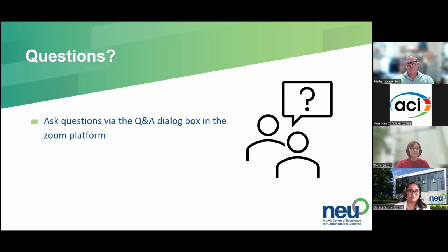And this code was written specifically for use with NRMCA version 3.2. Many of us have heard that NRMCA will be coming up with a new edition of the benchmark report soon. But this code specifically references version 3.2. Certainly an adopting agency could make an exception to that if they wanted to use some other local benchmark or even an NRMCA benchmark. But at present, the way the code is structured, those other concretes outside of that range are not part of the code.